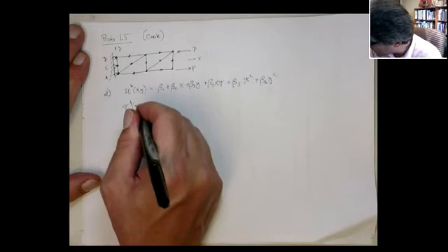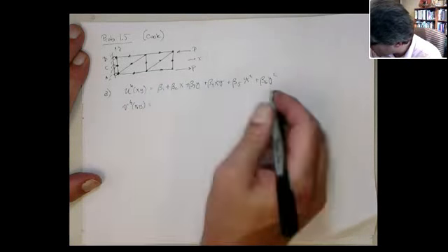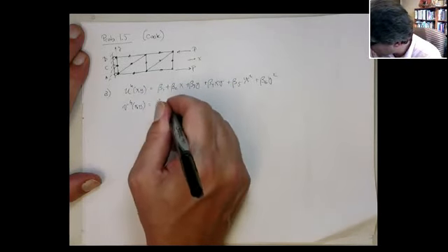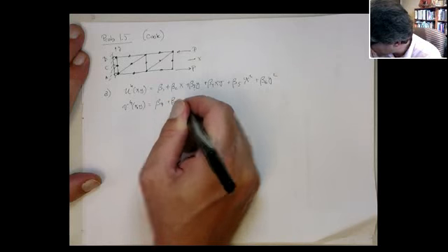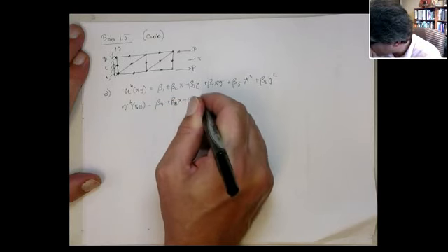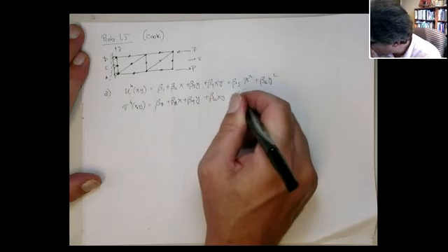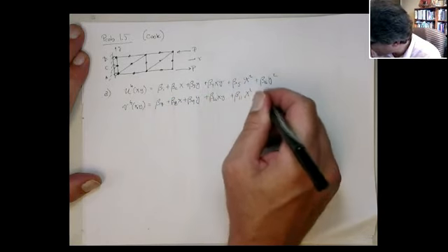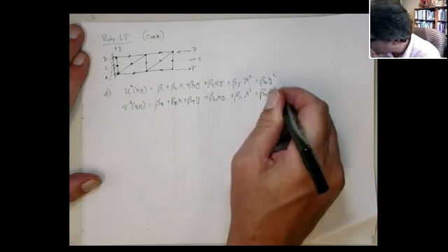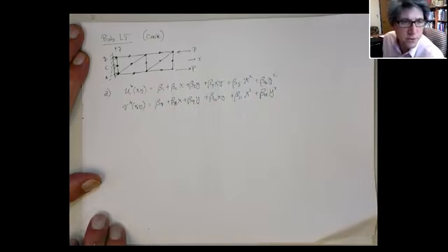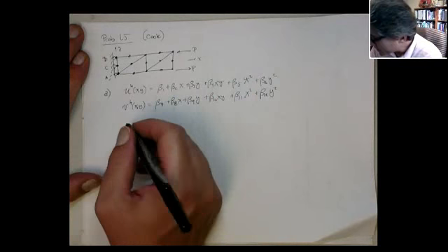The displacement in the y direction has the same form, but then we're going to start out beta 7 plus beta 8 times x, beta 9 times y, plus beta 10 times xy, beta 11 x squared, and then the beta 12 term is the quadratic in y. So there's the interpolations. All right, so this is just differentiation.